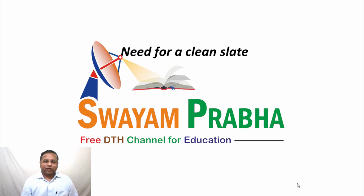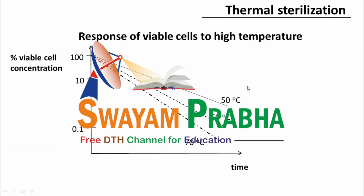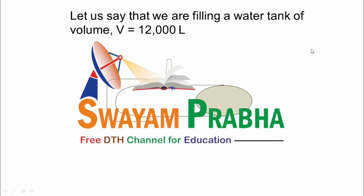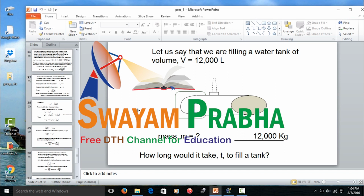Then we looked at the need for a clean slate. First we kill all the microorganisms in the bioreactor, then introduce the microorganisms of interest so that they can grow well and produce the product of interest to us. Some of the means of achieving a clean slate is high temperature, chemicals, and radiation. We looked at some kinetics corresponding to the high temperature sterilization or thermal sterilization, the concept of decimal reduction time, the basis of that, I will not get into that details in the summary. We looked at the material balance basics and so on.